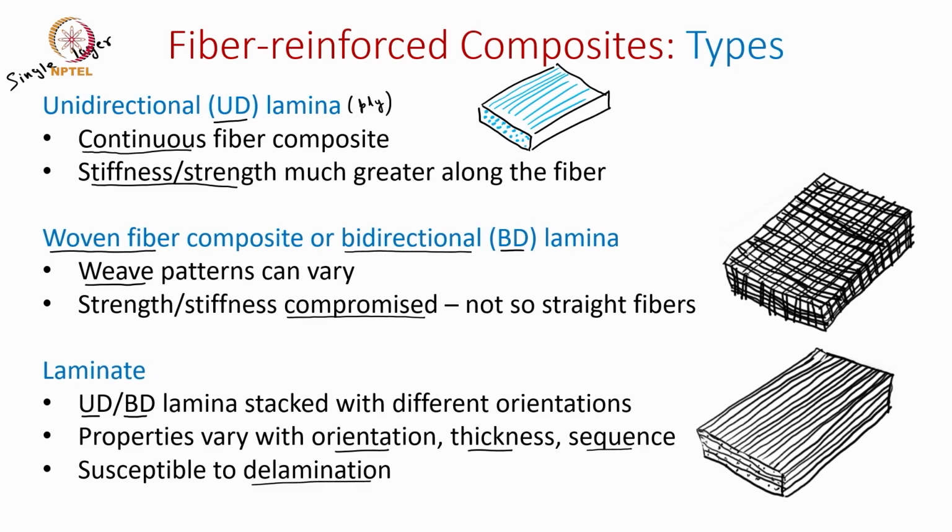Since we are discussing delamination, one more point is that woven fibers are less prone to delamination. The reason is that it is made up of a single layer, and nowadays there are automated machines which can do 3D weaving, meaning these weaves, instead of going with just one strand, can go deeper into a few layers of fibers and then come back.